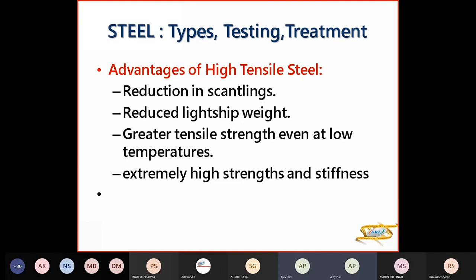The scantlings are the shipboard construction material used of various sizes on ships. So like you have your stringer plate, your girders, your strakes, your longitudinals, all are basically scantlings. Your beams, all these are, and your floor plates, all are scantlings.